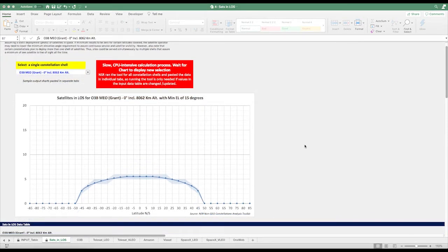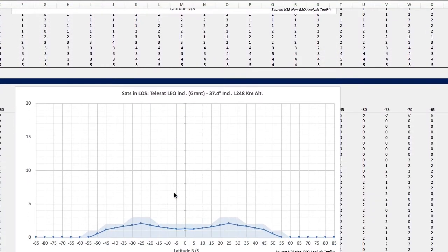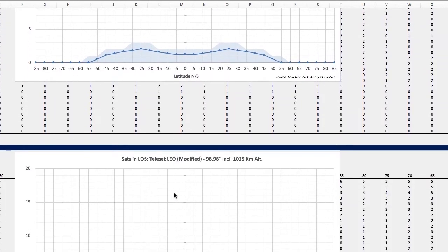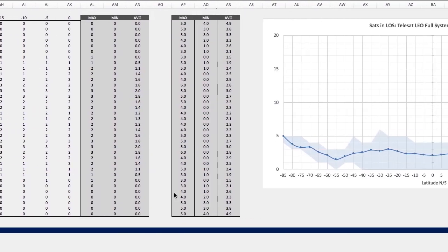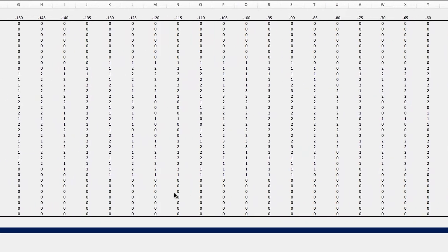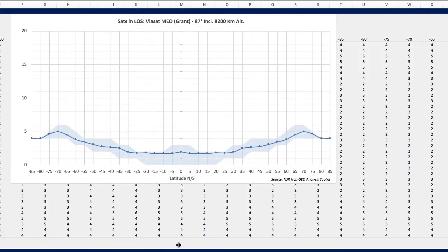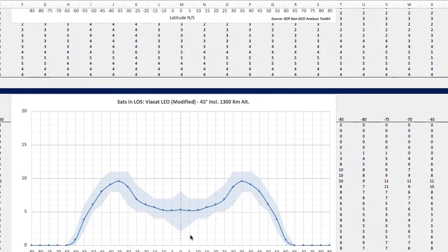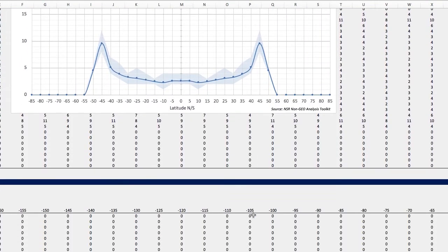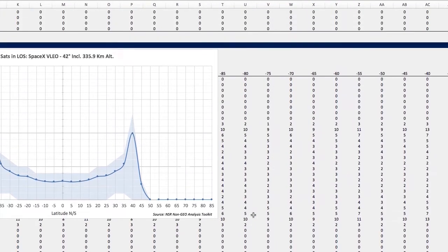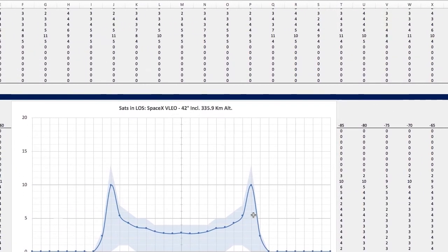The tool shows the new visibility chart and provides the output table used for the chart for users to leverage outside the tool itself, if needed. Note that if the minimum number of visible satellites results to be 0 for certain latitudes covered, this may not necessarily mean service interruptions, because the satellite operator may allow lower antenna elevation angles to assure continuous service and visibility. Also note that several constellation players plan to deploy multiple systems. Thus, sites could be served simultaneously by multiple sub-constellations with distinct orbital characteristics that assure a minimum of 1 satellite in visibility at all times.